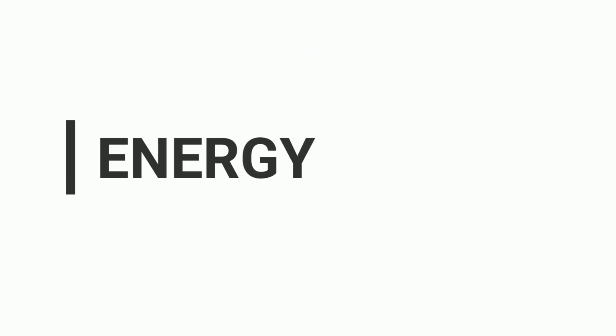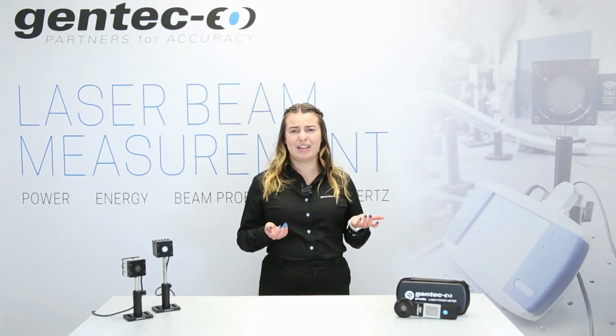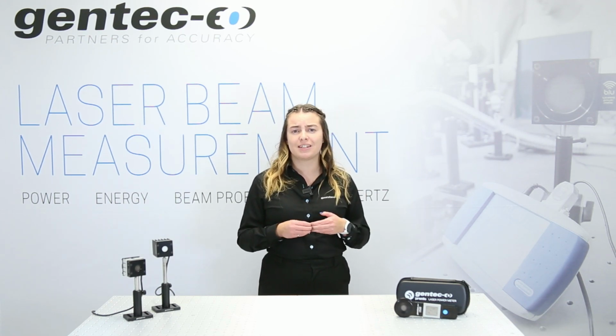Energy can be measured for pulsed lasers only. Measuring the average power can still give you information on the laser, but power detectors are relatively slow, so you need to have quite a big variation in the energy to be able to see it on the power detector. In order to know if the energy of every pulse is stable, you need to measure the energy of the laser. Not all pulse lasers require energy measurements. It is usually seen in applications that require fine-tuning of the energy, like the medical field, where every single parameter needs to be controlled.